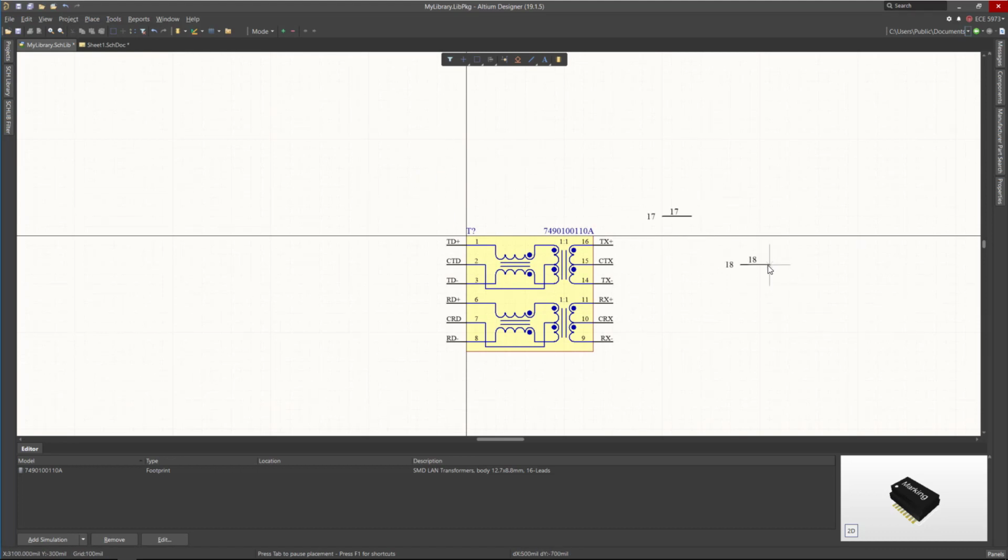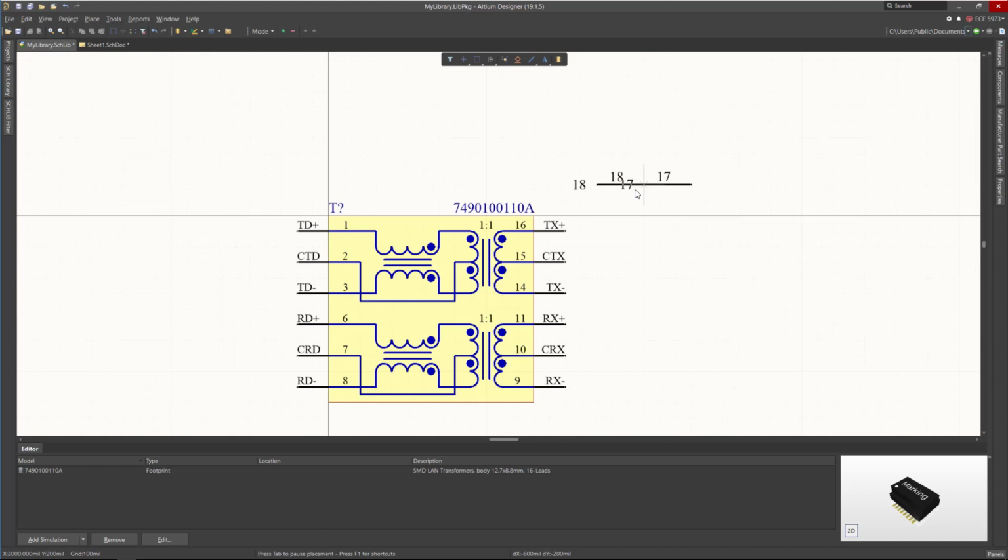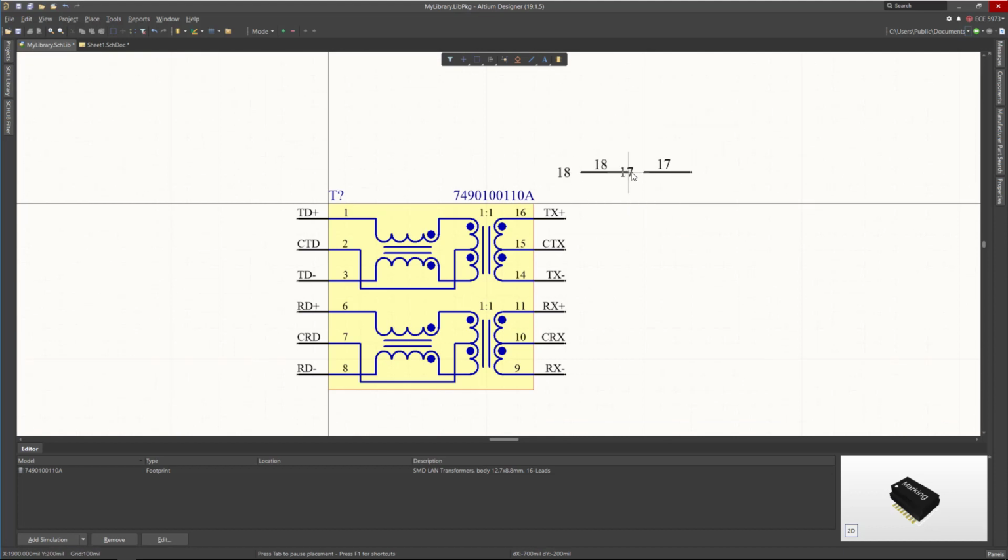Let's place it in here, for instance. And now, why does this pin have designator 17 and name 17, then designator 18? You see how the incremental sequence is automatic. Once you left click on the mouse, these pins will be added. Escape will cancel this command. In the same way, you can add pins from this panel in here. So you have a pin in here, you can continue.